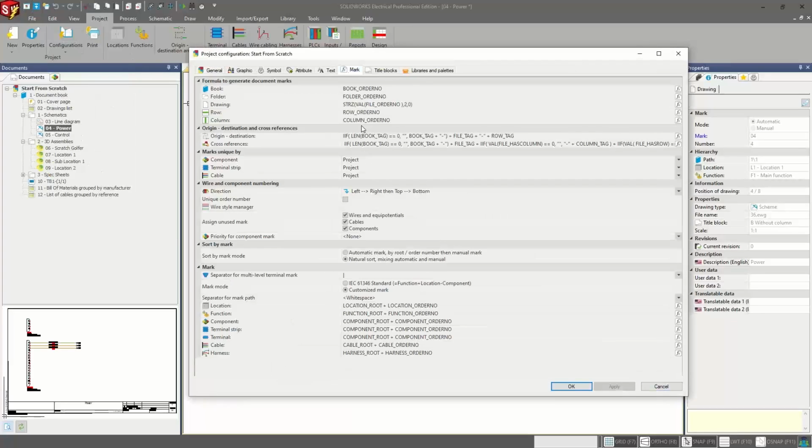You have the ability to change the row, and you can utilize these fields here for your wire numbering scheme as well. Based off of that, setting up the rung is another step on top of that. You have to set up the wire formula scheme for those wire styles that you want on that rung, that ladder logic look, right?